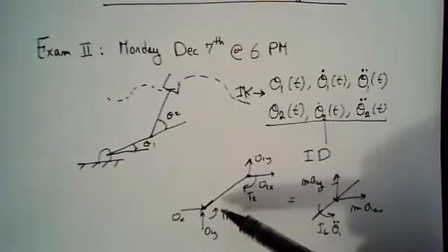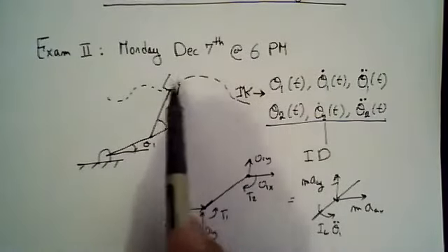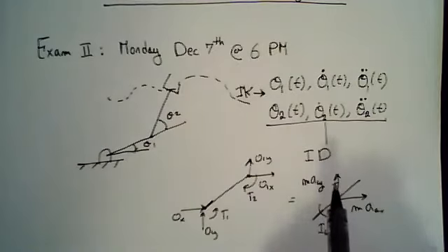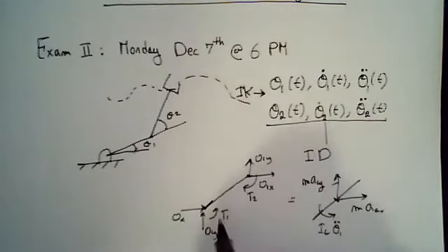So we use inverse dynamics to be able to compute all of these, given that we assume the movement. So given that the movement has already occurred along this path, what are the torques that are on every joint, and what are the forces which are acting on all the motors. Okay, so inverse dynamics is great if you actually have a path, but it doesn't actually tell you how to command the torques. Well, it will basically tell you how to command the torque in a sense, what should be the torque, but most of the time, the mass here, the I_g is not very accurate, or the links may not be 100% exactly what you think your computation is, so you will actually have errors.